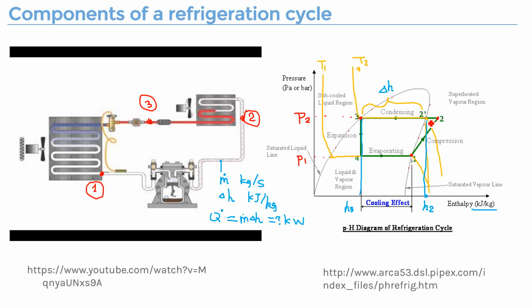Ideally, all the vapor will be cooled down, or not really cooled down, but reject the heat and have the phase change from vapor to liquid. So you will observe no temperature change, because if you follow the orange line, the temperature is constant. So here at point 3, it's still pressure 2 and temperature 2. And now the last step would just be from point 3 to point 4.